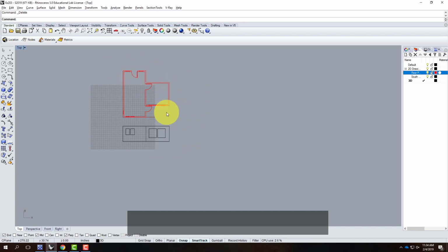The colors don't reflect it. They're not important long term. If it helps you to have lots of colors, you can assign lots of colors. If you like to work all in black, you can leave it all in black. It's really a personal preference. The one thing I will caution you against is to not make any layer yellow. It'll let you make a layer yellow.